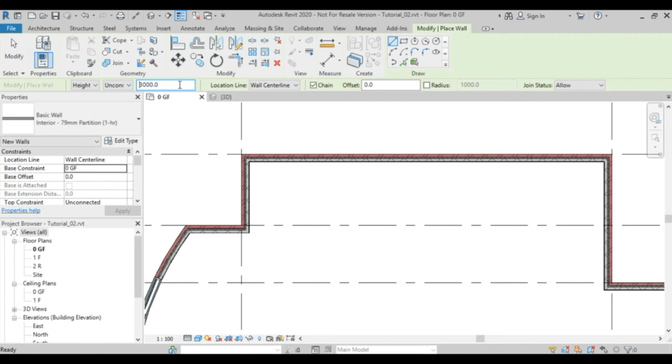And it's very simple that we specified it 3000 because we left almost 1 meter, 1000 millimeter, for the ceiling and whatever utilities above the ceiling, from HVAC, cold water, hot water, and sanitary, that go over the ceiling. So 1 meter will be good enough for this small space or this small office building.